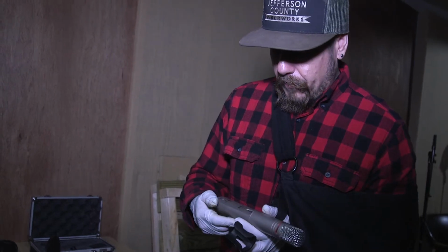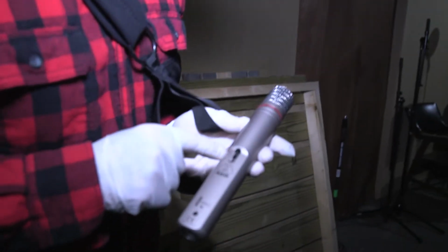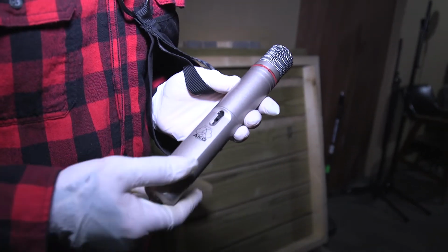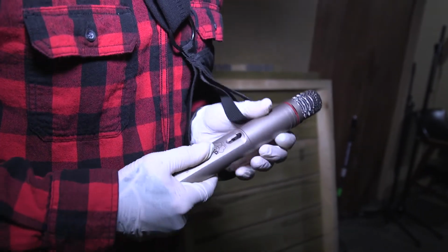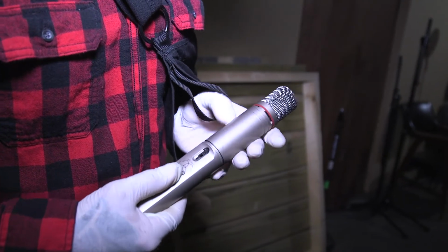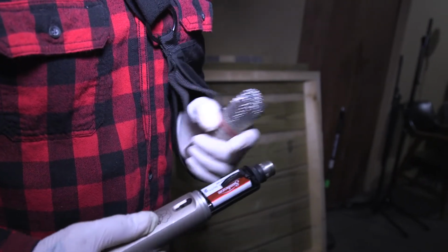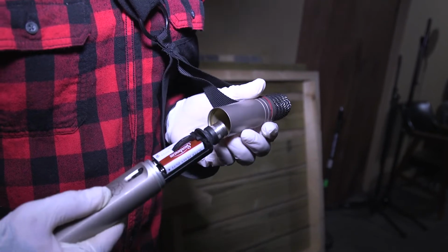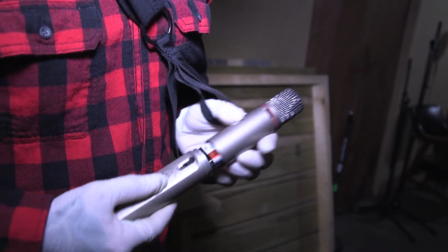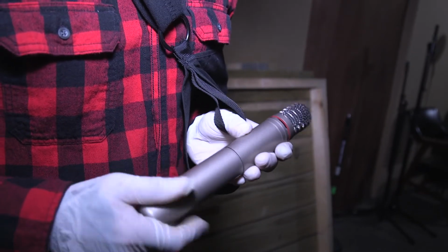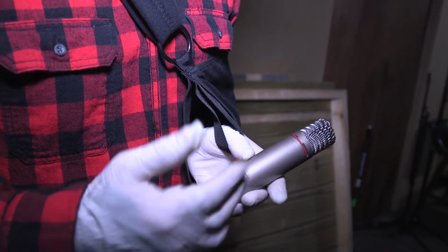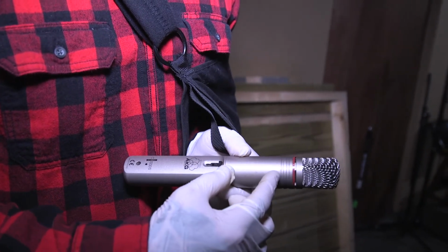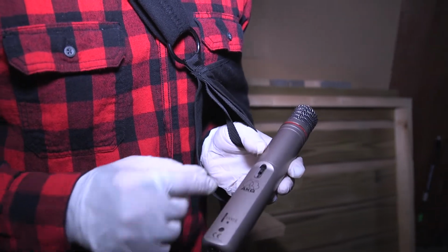So this microphone is interesting because it's a condenser microphone, but it also has an on-off switch. And this is because this microphone can also have its own preamp. Essentially, it has its own power supply. If you unscrew it, you can see that it has a 9-volt battery in here. And so this is just in case you don't have a preamp, but you have maybe an input on an interface or something that doesn't have a preamp, then you can actually power this microphone with a battery, and it will supply its own phantom power.